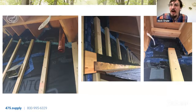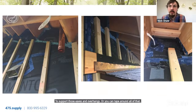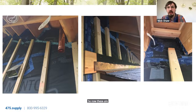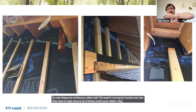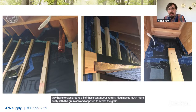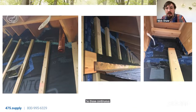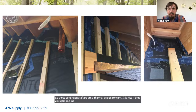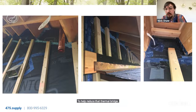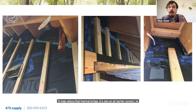Or you can tape around all of that. So now these are continuous rafter tails. This wasn't monopoly framed, and now they have to tape around all of those continuous rafters. Energy moves much more freely with the grain of wood opposed to across the grain. So those continuous rafters are a thermal bridge concern. It is nice if they could fill and insulate that soffit space to help reduce that thermal bridge. It is also an air barrier concern. So now they are having to tape around all of these.